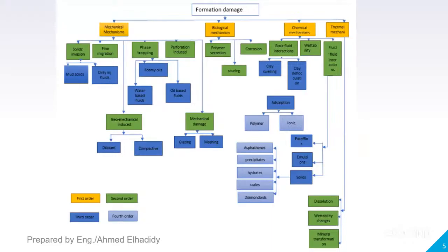The critical point we need to highlight here is that before you conduct any operation, even a recompletion, remedial work, or a well intervention such as well stimulation, you should define your type of formation damage to select the optimum treatment to solve what you have. Because if you fail to define your problem, or what type of formation damage you have, you will select an improper treatment and cause more damage than what you have.